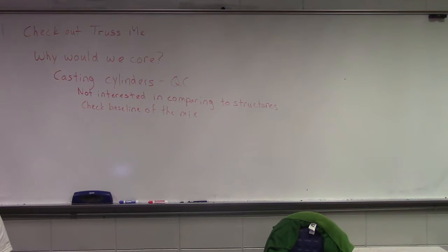If your compressive strength comes back fine, a structural engineer might sign off on it, and may not need to look at it. I personally would have it looked at under the microscope just to make sure they don't have a lot of breakup, a lot of localized high water content at the top of that concrete.